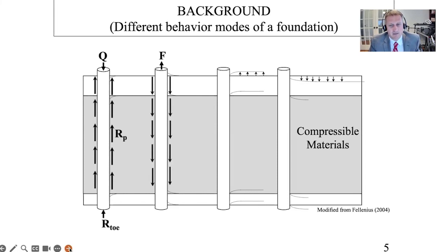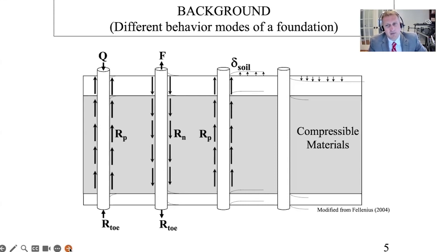That force is acted against with skin friction acting along the pile. And then we also have some suction type of toe bearing resistance that would happen at the toe of the pile. So both the downward and upward mobility of piles, whether it's in a compression or a tension type of state. So if the soil is expansive and it moves up on the pile, that could cause resistance to develop along the pile as well, and we would have negative toe resistance.